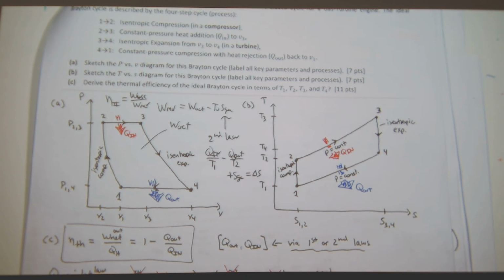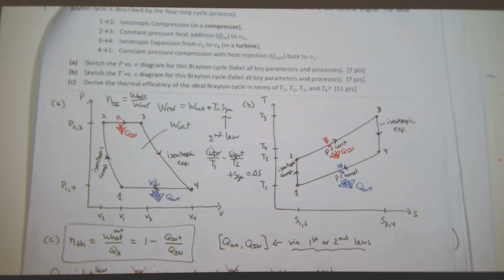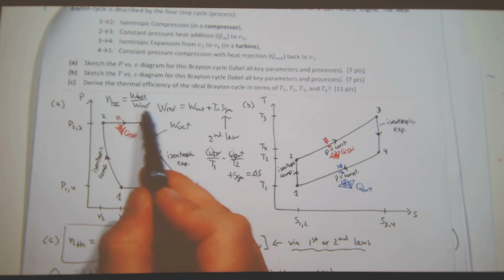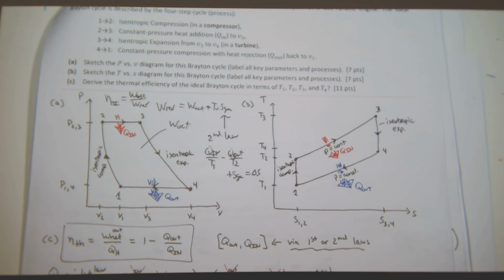Those are the boundary temperatures. And for power producing, is this work actual plus T0 S gen? Oh, yeah, thank you. Yeah, because you want this number to be bigger and bigger. But you get the general idea how you can calculate the second law or the first law efficiency. I just did thermal because there's this simple expression, and it gets you to think about entropy and energy balance. This is even a better problem, but I think that's beyond the scope of the course right now.